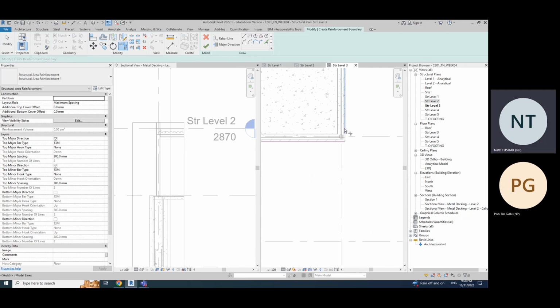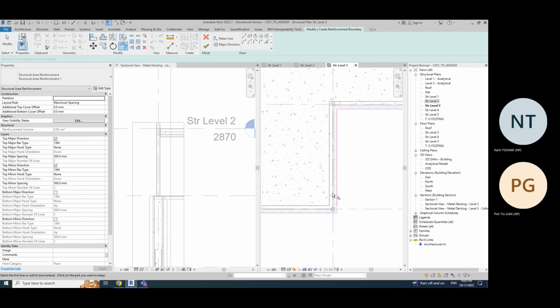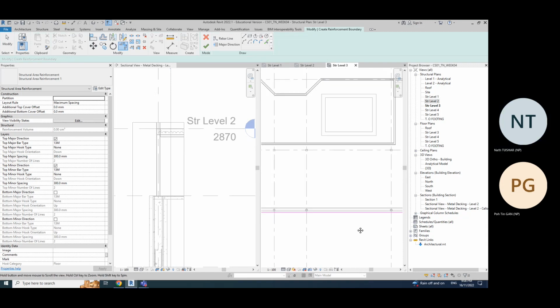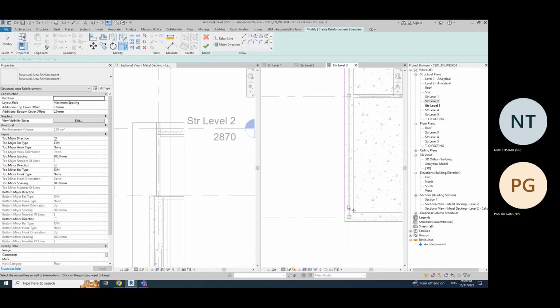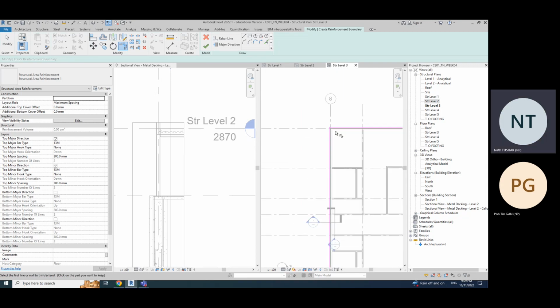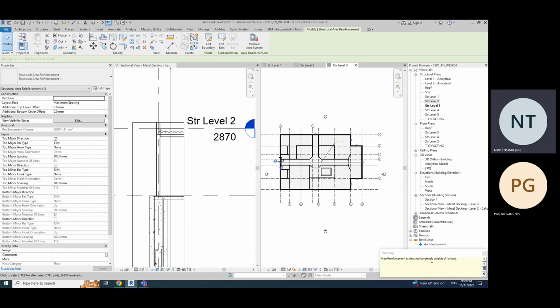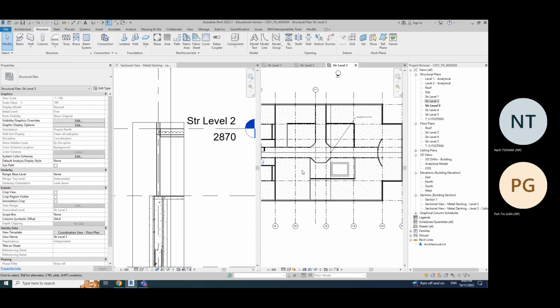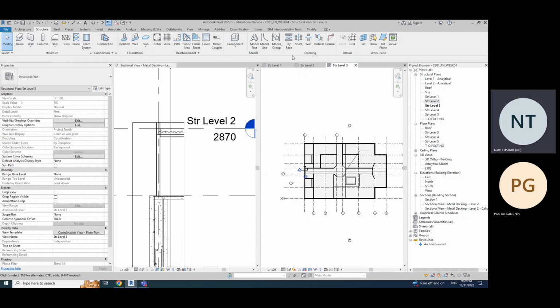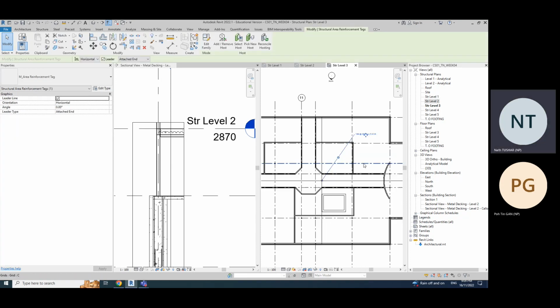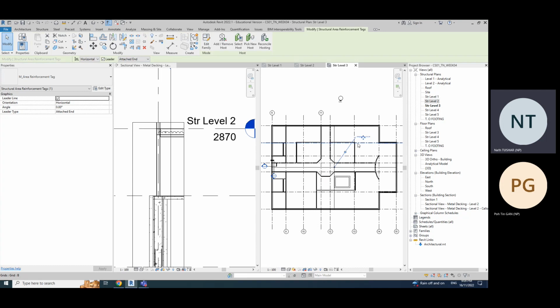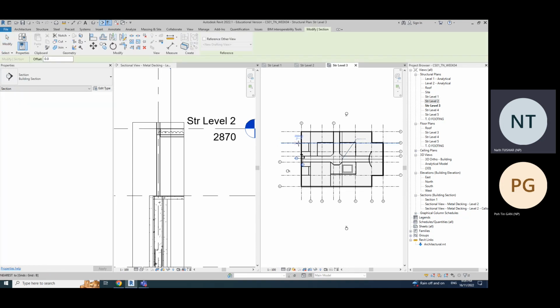Okay. So it may or may not happen for you, but good to know that you have software come to your rescue. Okay, once it is done, hopefully no more error. Complete sketch completely out. Okay, so I drew my area reinforcement just now, which was at 300 mm spacing. Now I want to see the section view of this one.